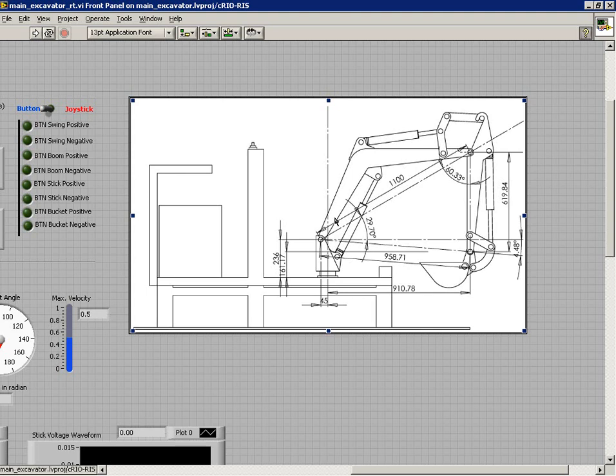We cannot control the speed, we cannot change the PWM, so we cannot do the end effector control, robotics control. So we change that on the swing and on the bucket. We need only the PWM. However, for the boom and for the stick, we change using the proportional control, the DAC.